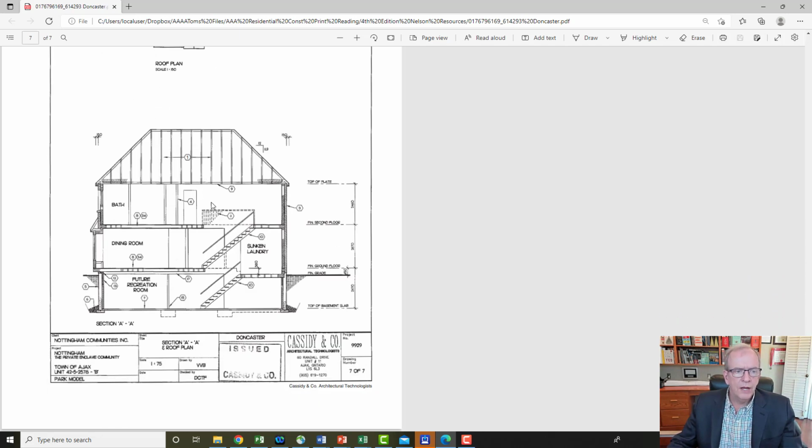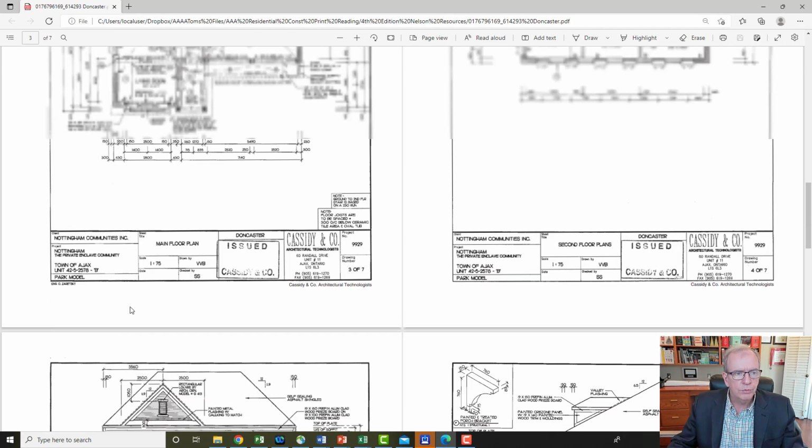So here we've got another orthographic view, which is a straight cut through of the entire building. So we can actually see inside the basement. See, we're talking about the basement on this particular set of drawings. We can see footings down here. We'll be looking at those in a moment. And this is cut through, and it's called section AA, and it's cut through the floor plans.